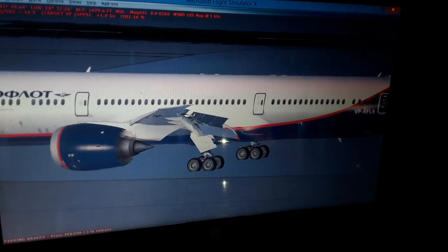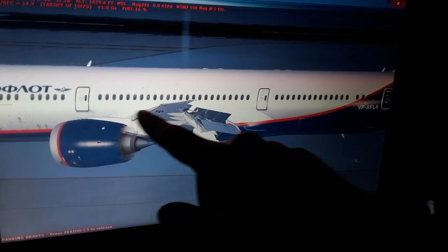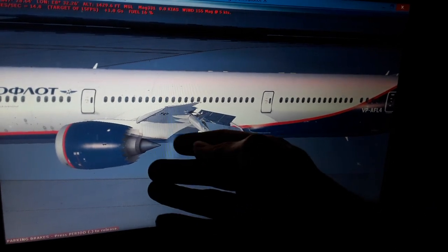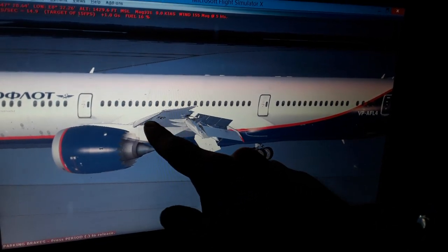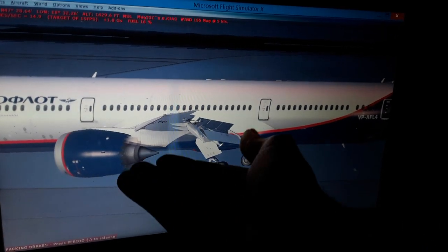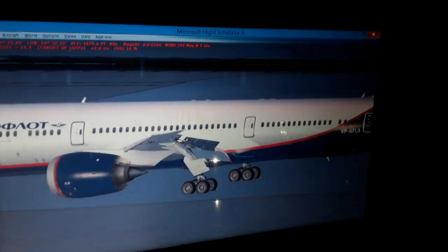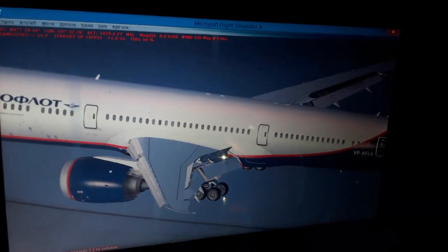You can see the bottom surface is more flat, and also we have the curvature from the flaps. So as we take off and then fly, using the Bernoulli theory of fluids, the airflow is moving slower below the wings. So we have higher pressure of air below the wings, which pushes the aircraft wings and weight up into the air.